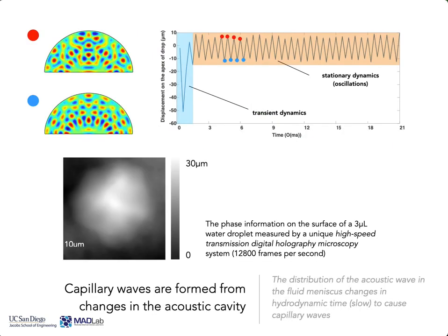But in any case, the reason is that when you have the fluid droplet trapped on the surface, it forms an acoustic cavity. And so if you're designing some of these devices, like with orifices or other things, it is important to remember that you're forming an acoustic cavity where the acoustic wave will set up a standing wave in the system.